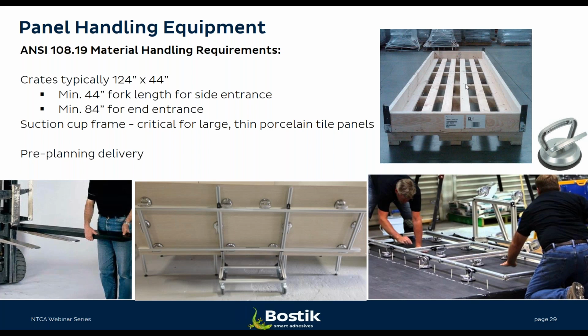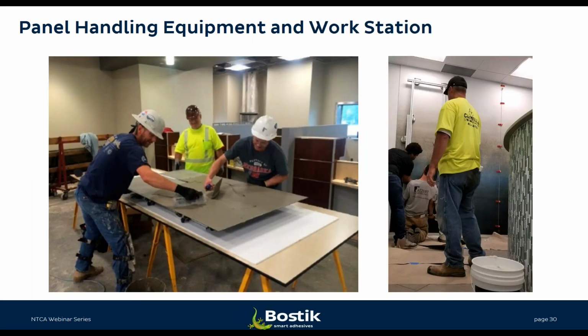And then you'll see in the marketplace a variety of different suction cup frames that are critical for maneuvering these gauge porcelain tile panels, installing them, and then they'll even hold the material while you apply adhesive or mortar onto the substrate. You'll find that installers have found a variety of their own ways, aside from using the standard tables, although they're still using the systems of suction cup racks for holding the materials and transporting the materials, but building a variety of different substrates or surfaces to work off of so that you can have a flat surface.